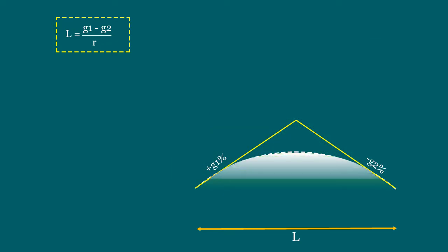Now, we will see what type of curve can be used as a vertical curve. Either a circular curve or a parabola may be used as a vertical curve. In a parabola which has a vertical axis, the rate of change of grade is uniform throughout the vertical curve. So, parabolic curves are used as vertical curves.